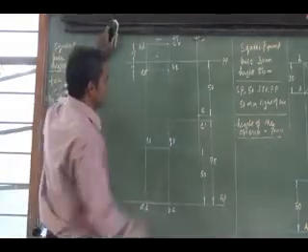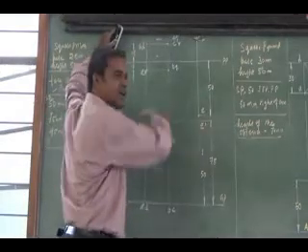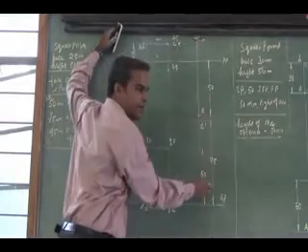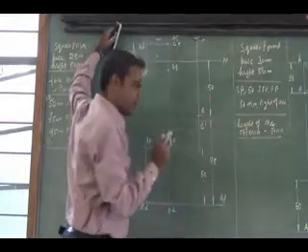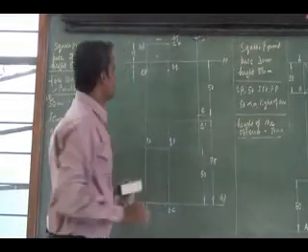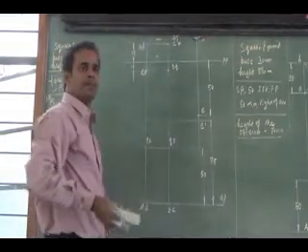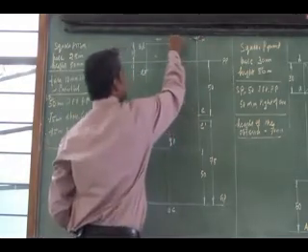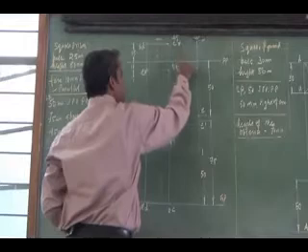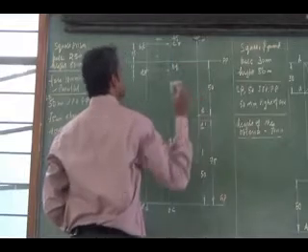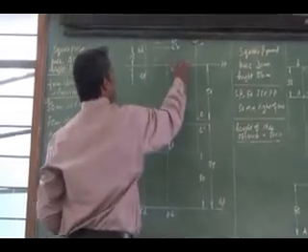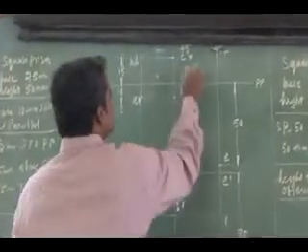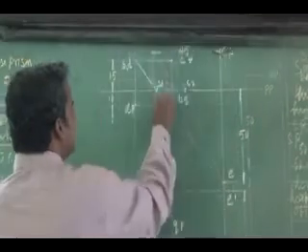Then the station point location is given. It is to the right 45 mm, the in front of distance is 50 mm and the above distance is 75 mm. So the layout is drawn. Then you get the perspective view. You get the intercept of each corner by joining it to the station point. Similarly, what is the intercept location for CR? The CR intercept location is there.